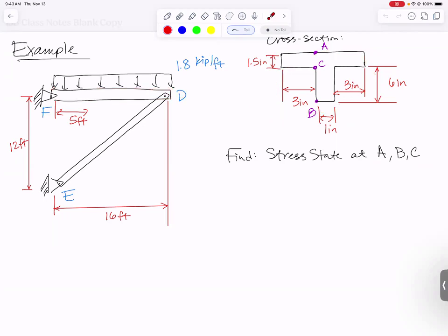And it might be a little while since you've done statics. Do you recognize that member DE is a two-force member, which means all it can do is apply tension or compression along this axis that's lined up with it? So we can jump straight to drawing a free body diagram of member DF, and we will then find out what the force in this two-force member is that's probably pushing up to hold the beam up. Also, what are the reaction forces out here at point F? And where we actually took that cross section was right here, 5 feet away from point F.